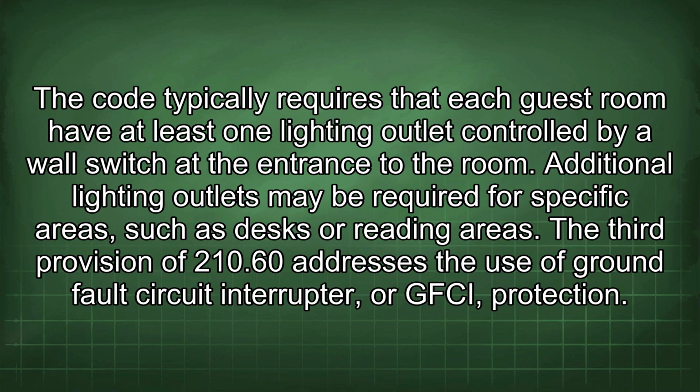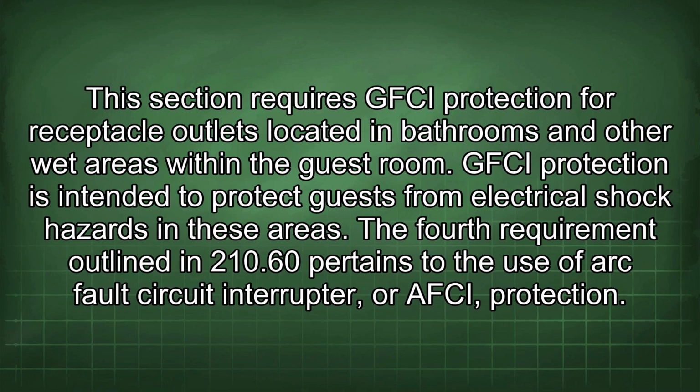The third provision of 210.60 addresses the use of ground fault circuit interrupter, or GFCI, protection. This section requires GFCI protection for receptacle outlets located in bathrooms and other wet areas within the guest room. GFCI protection is intended to protect guests from electrical shock hazards in these areas.